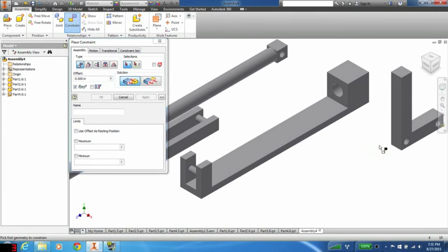So I'm going to start with the face on the inside here and on the back of this shape because it's in the orientation that we want it. So instead of moving the camera around the shape, I'm going to hover over where I think the backside is approximately and just wait a little bit, and then you can see we have a drop down menu that pops up. I'm going to go over until I get face normal, and as you can see, the face on the other side highlights. That's good, so I can select that.